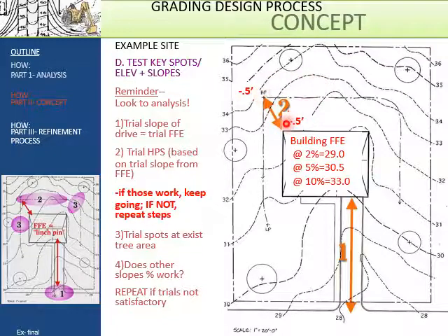So for example, if there was a 10-foot difference between the corner of the building and the location of the high point, that is your H is 10 feet, then going down with a V of 0.5 means you've got a 5% slope there. You could do it as a 2% slope if you wanted, that would be fine as well. But we're making this fairly simple right now. We're dropping down half a foot to the corner of the building and half a foot to the high point.